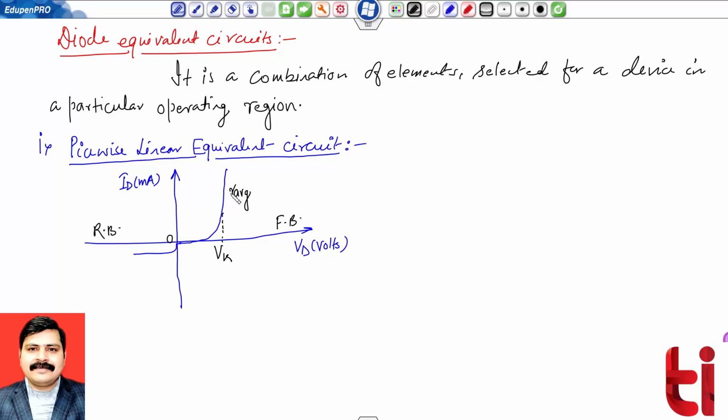We have studied in the previous session the different resistances of diode. So what is the requirement? As we are dealing with the diode, this is the symbol of diode, representing suppose with D, ideal diode. What are the components involved over here? For simplicity, I am taking the example that I want to prepare the model for a diode manufactured from silicon. So in this model, the first component will be the diode itself. It is my ideal diode.